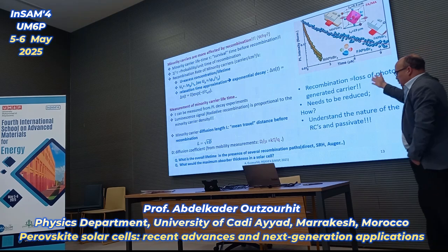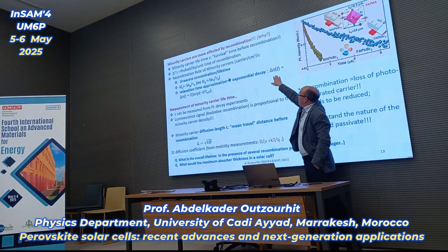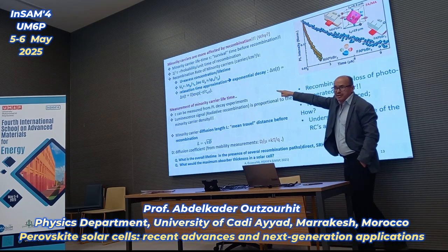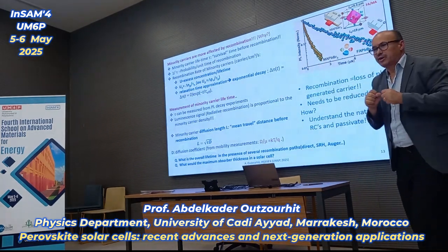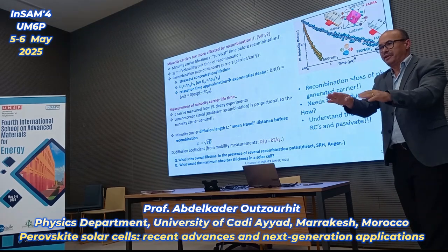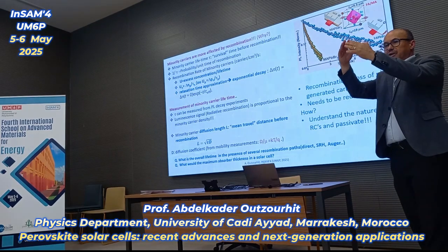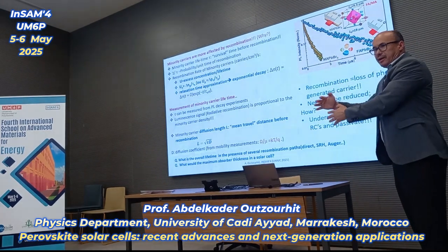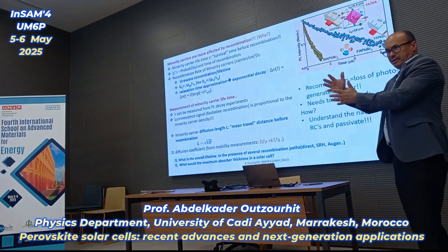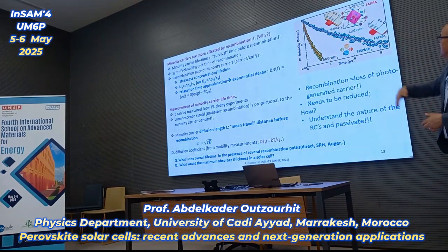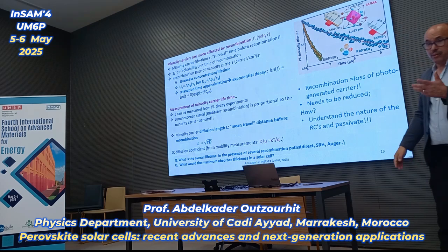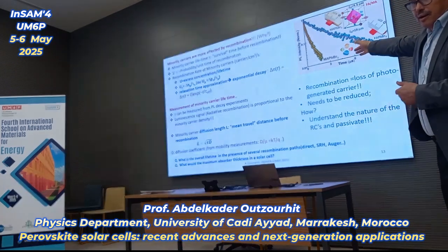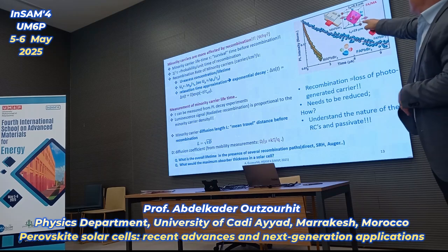This will give you an exponential decay of the carrier concentration. Just imagine you shoot a photon pulse on the semiconductor and then stop it. You create an excess and you let it decay. It decays because of the recombination. So we get a decay, and from that decay we can get the carrier lifetime. And this is the photoluminescence decay.